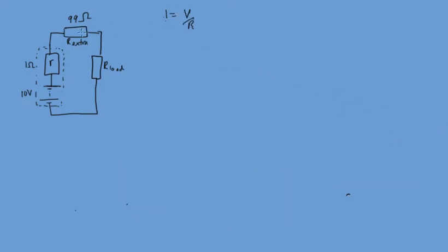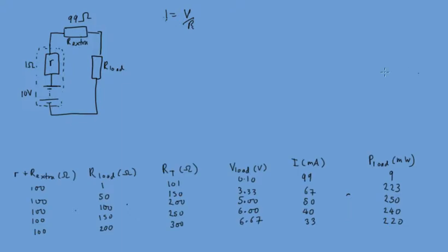So by increasing the resistance, we can decrease the current, and we can control the current going through whichever device we have here, and we can protect that device from having too high a current, because that can be dangerous. It can get really hot, it can be a fire hazard, or it can just break your device. So let's look at what happens in this situation.